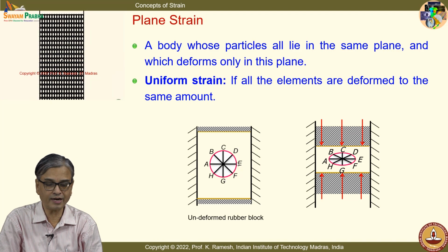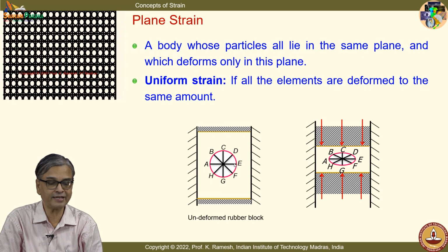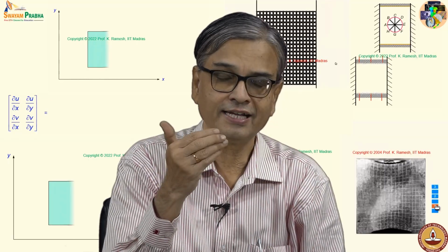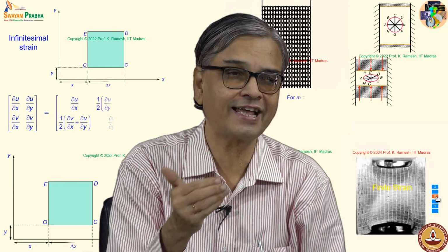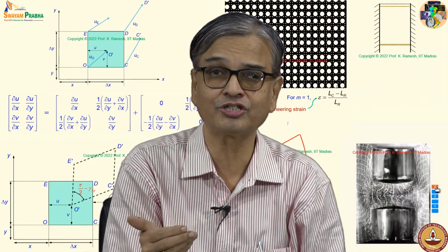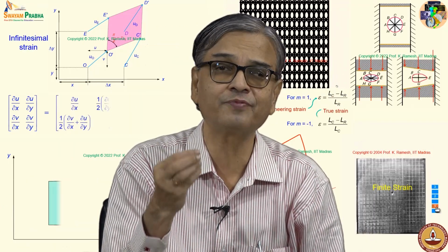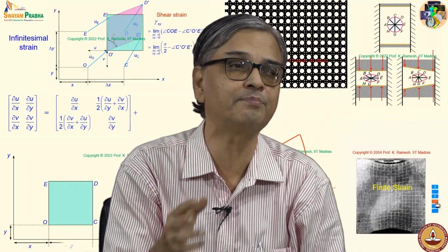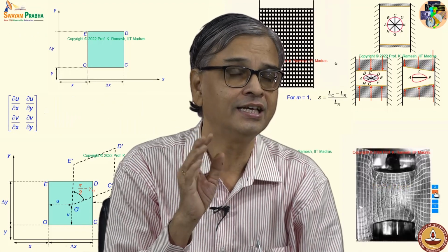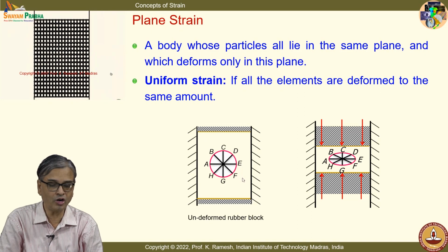And you can also understand, like in the case of stress, when this line element AA shrinks to 0, we get strain at a point. I raised a question whether strain is a scalar or something much more. We raised a similar question when we developed stress. It appeared like a scalar to start with, because when you look at components, they are always numbers. They will appear like scalars, but the entity is not a scalar entity. Like stress, strain is also a tensor. And you have all that understanding here.